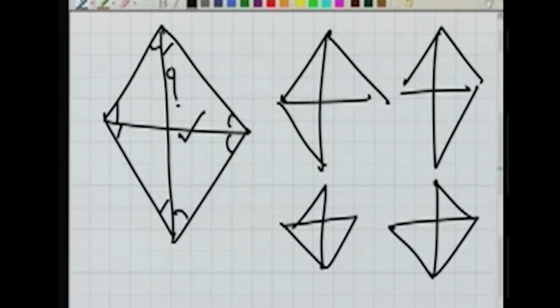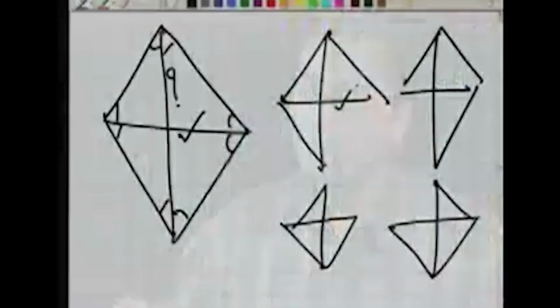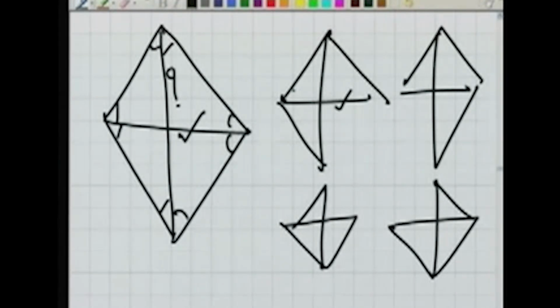Now when we start computation, starting from the known length, we make use of the sine rule, so we are including some angles here. Let's say we want to compute now this length. So we are including this angle and this angle in the computation. Then once we know this length, this was AB and CD. So once we know AC, starting from AC, I want to compute again CD. So again I am including the angles at D, this ADC, as well as the angle CAD.